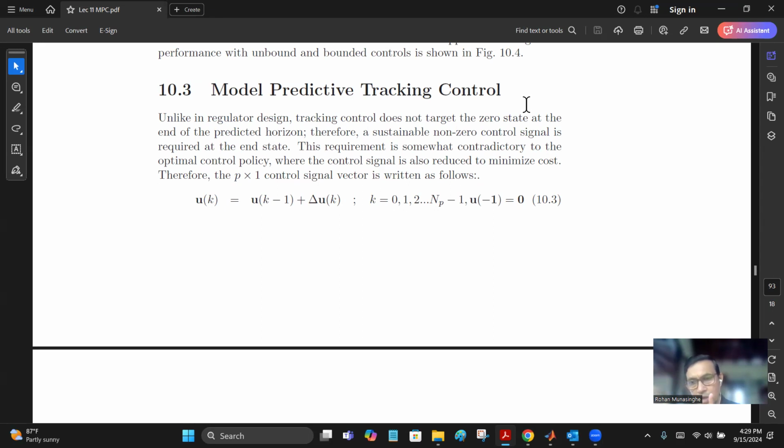When you have +1 and -1 cancel out, it feeds back to the linear quadratic regulator a 0. Then the linear quadratic regulator thinks everything is fine because the state is now at 0. But in fact, the state has already been driven to 1, right, without the knowledge of the linear quadratic regulator.